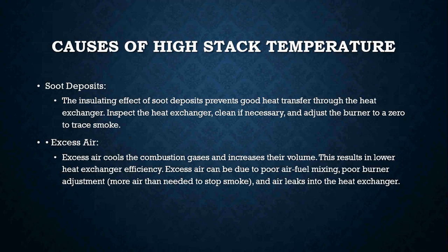Okay, and leaks into the heat exchanger. You have to make sure that your burner is sealed. Your gaskets are in place. There are no areas of air that can come into that burner other than where we want the air to come into that burner, which is through our air collars.